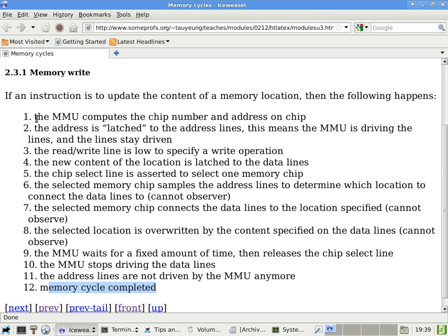Yep. But that's only if those next addresses are on the same chip, right? That is correct. When you do DDR2 and DDR3, this is what they call a burst mode read or burst mode write. They can only happen to a block within the same memory module. So there are restrictions as to which sequential locations you can read sequentially using this particular burst mode of operation.